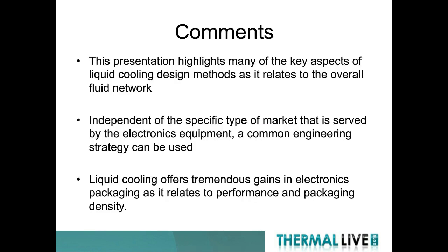So some comments. Again, this doesn't answer everybody's question on liquid cooling, but it starts bringing to the forefront some of the key engineering strategies of solving it. And so that's what we're really looking at: what are those liquid cooling design methods. We talked about CFD that's used at the cold plate level, calculating pressure drop. We use many different methods. MacroFlow is a common software package, and there's a lot of different ways of calculating the pressure drop.